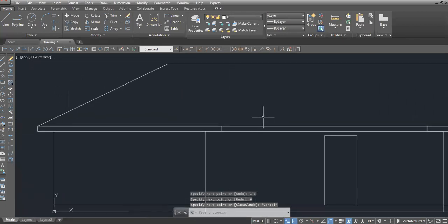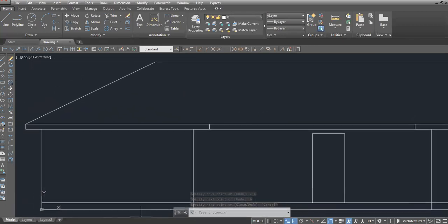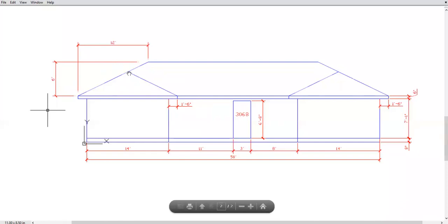And the last thing is, all right, we go back to our PDF, we need to draw these lines. You can see that this is centered between this line. So what I'll do is I'll draw a line from here to here. Then in the midpoint of that new line, I'll draw a perpendicular line. And then the intersection of that perpendicular line to this diagonal line we've already drawn, I will draw a line from here to here and repeat it on the other side.